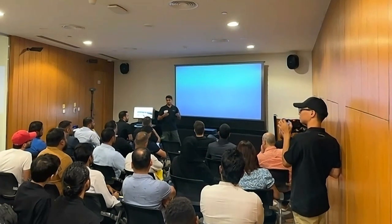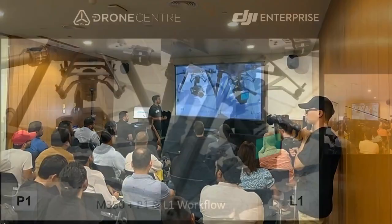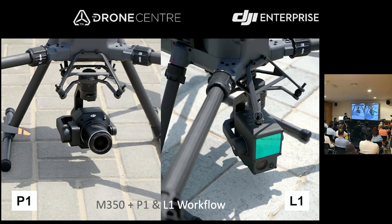But the next thing would be the flagship Matrice 350 drone, which I mentioned. So we are using Matrice 350 with both P1 sensor and the L1 sensor. As you can see, the L1 sensor is called the LiDAR sensor with the CMOS sensor. So the LiDAR is used for taking all the point cloud references to use for your 3D modeling, or even in public safety, they are using the LiDAR sensor to detect any object underneath, because normal camera payloads cannot penetrate deep vegetation.